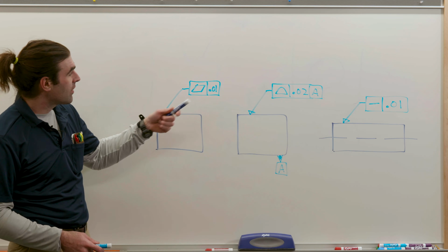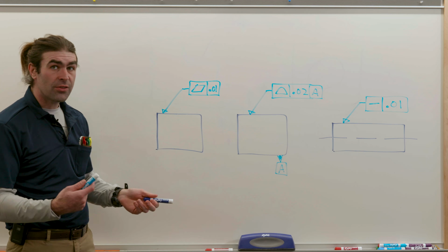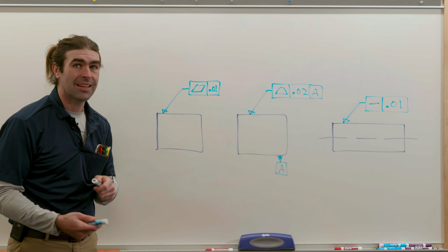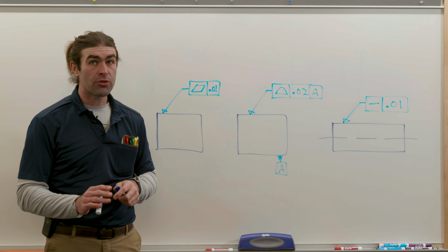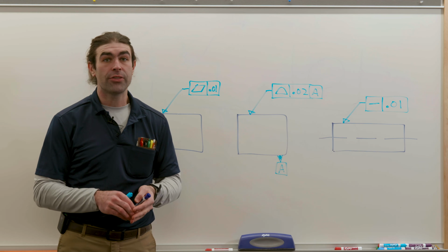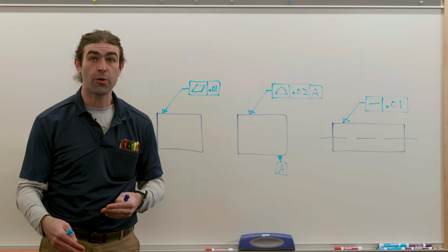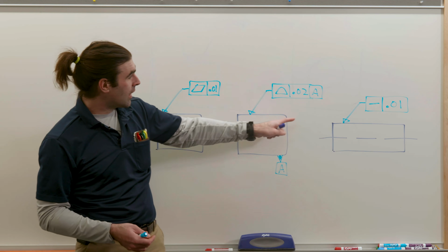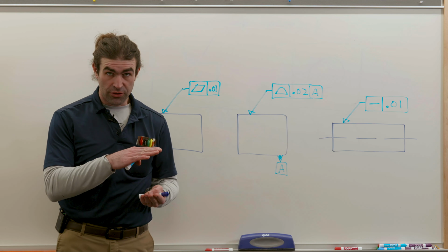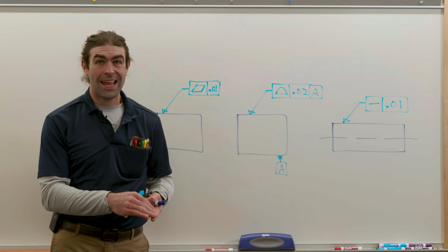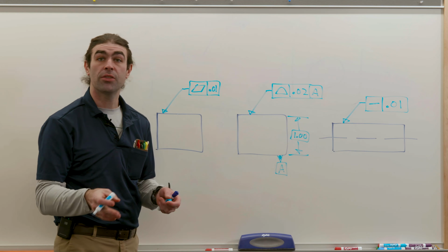So in this case, a flatness tolerance is directed with a leader to a surface. It's just saying that surface is flat to within 10 thousandths. Next up, we've got a profile, which is very tricky. Profile can do a lot of different things. It can function just like flatness, or it can locate surfaces. In this case, with a datum reference to datum A, it's doing the job of flatness, parallelism, and locating a surface if we have a basic dimension.